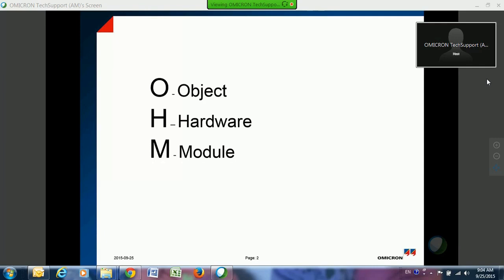But also in the object file, you'll set up some global settings, such as whether it's two-phase or three-phase. Typically, we're working with a three-phase system, but sometimes you may get into a railroad that may use a two-phase system. You can also put in the frequency, and information such as primary and secondary values for your CT and PT ratios. That's one thing we'll be visiting during the initial part of the Quick CMC.